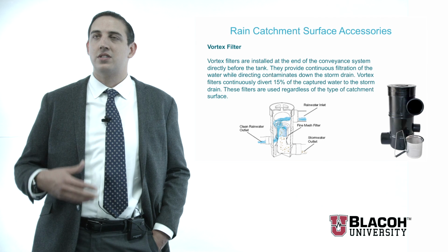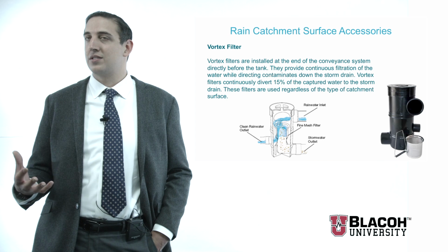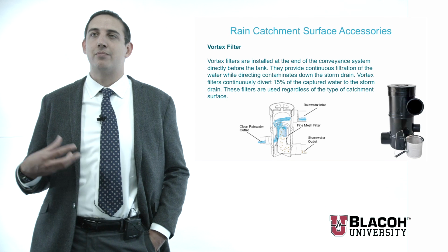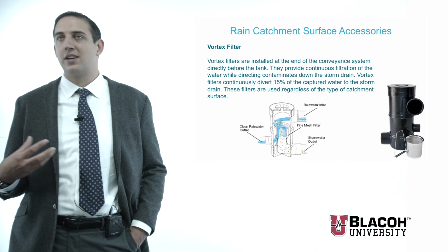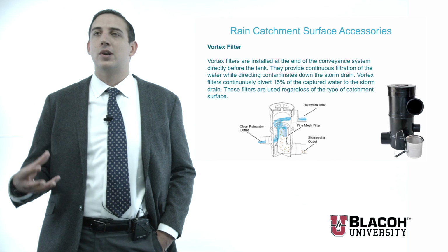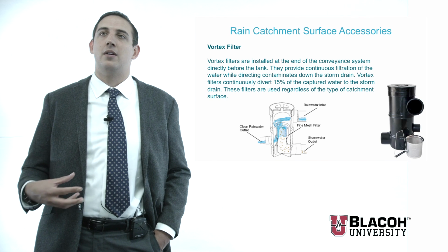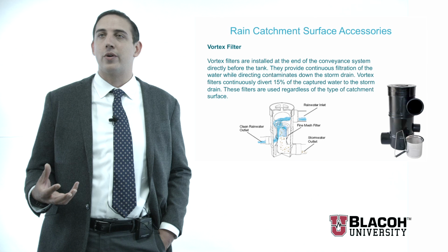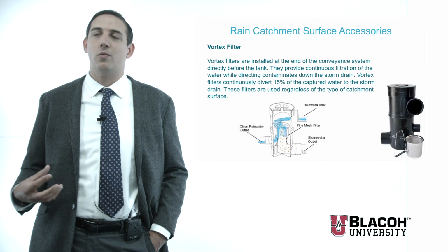If you're talking about a building which is 10 stories tall, and the water comes down, you're going to basically destroy the system. They're just not designed for that kind of pressure, and they're really not designed for the very high flow rates that you typically see in commercial buildings. So people are using things like, now they're developing concrete separators, they're converting basically oil-water separation systems that are now being utilized for rainwater systems.